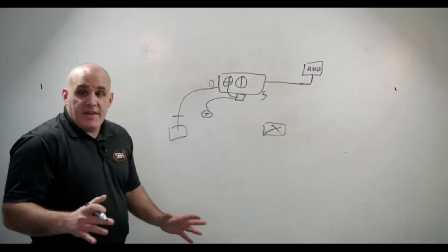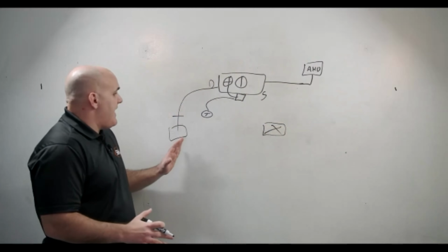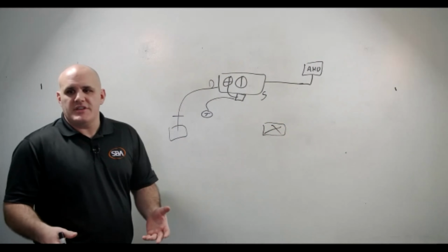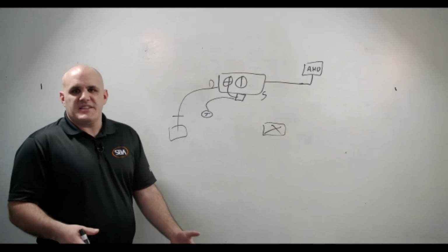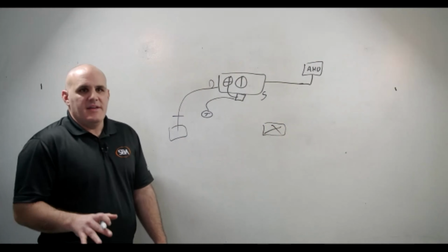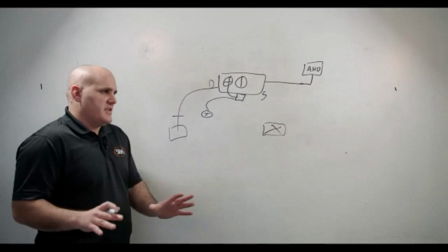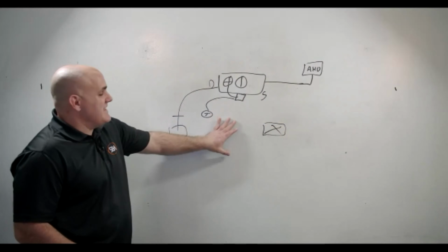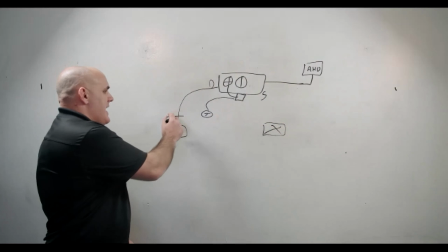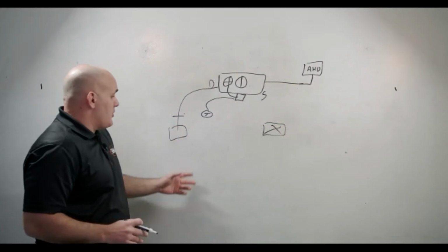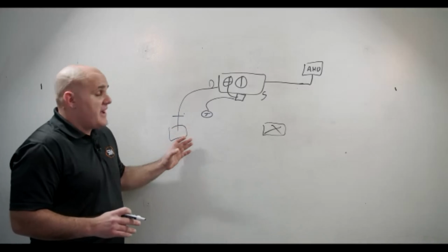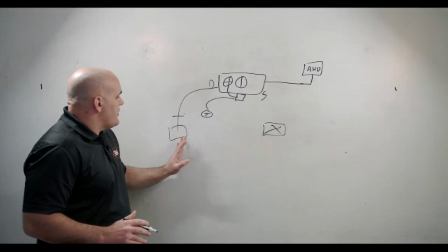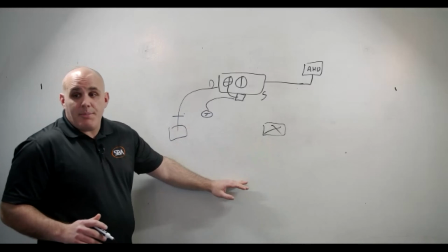Because remember, how spaces work is we have air changes. Technically it could be some third-party heat source, like someone having a desk heater under their desk, or windows being open, but let's throw those out for simplicity's sake. We have supply, and we make sure that the balancing damper right before the diffuser is open, so we're getting the right airflow out. And then we make sure that we're exhausting properly, and we make sure that the throw of our air is proper to mix.